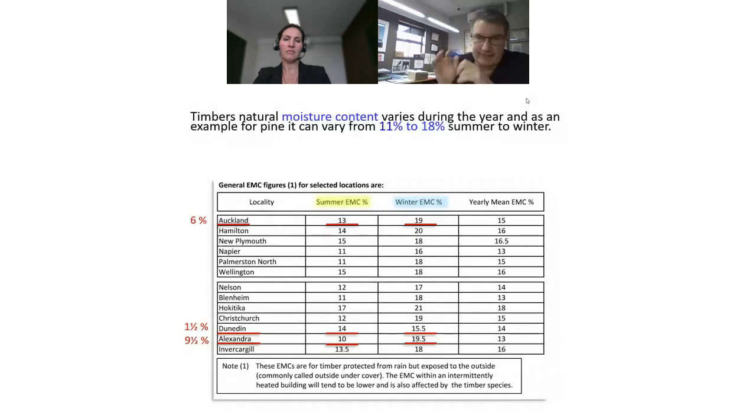A lot of people, and the reason that's there, especially when I'm teaching my staff, is a lot of people that grow up in Dunedin and get old and retire, guess where they move to? Central Otago. And so again, they might have had four weatherboard houses in Dunedin over the time of growing up, and then suddenly they move to Alexandra and wonder why their boards are moving more than in Dunedin. So again, it's just very interesting stuff. But once you understand timber a lot more, then you can work around it and you allow for it.